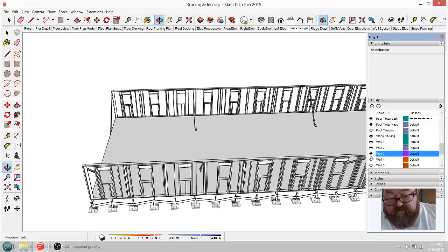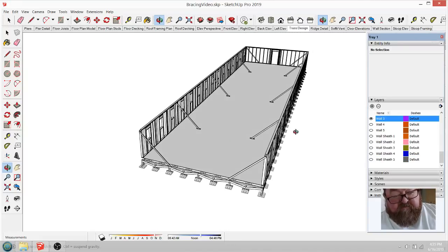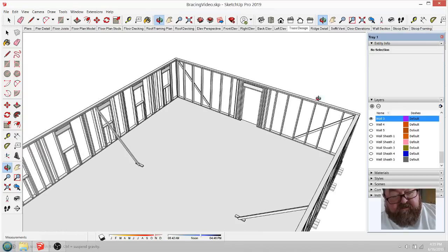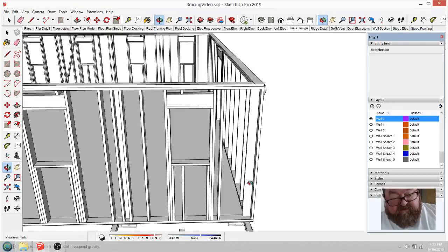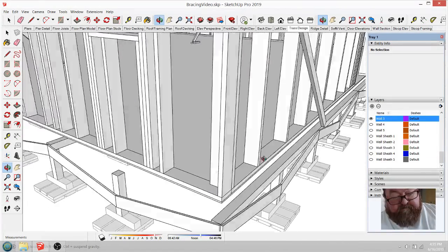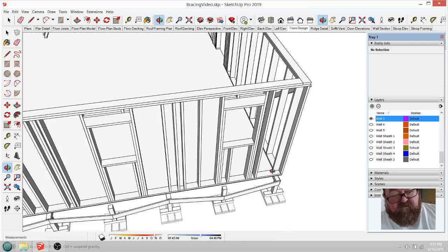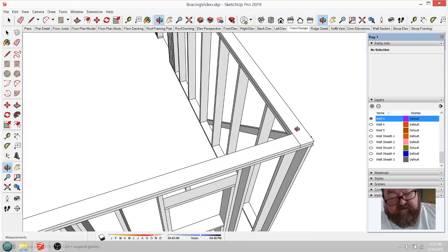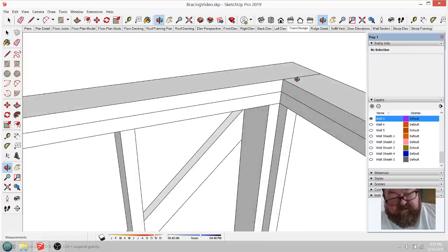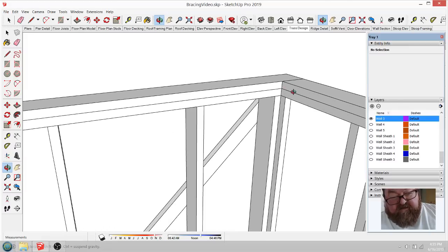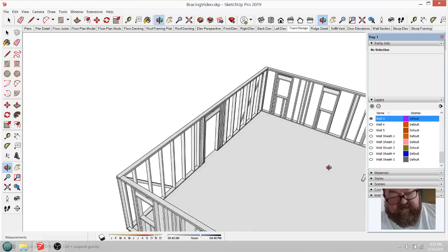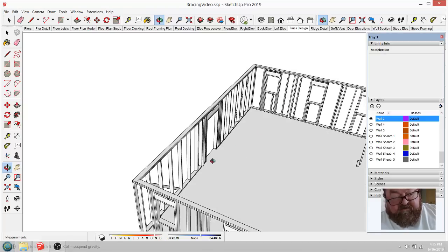build wall number 3, because you build your first two, your longest walls, first. Let's go ahead and demonstrate this, because I'm going to drive this home. This wall here is built. You can't see it because the top plate overlaps, but this wall is inside the two outside walls. So that means it can be built on the floor, laying down, after these two walls are up.